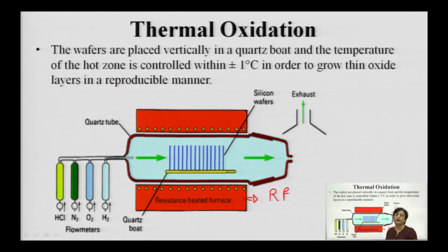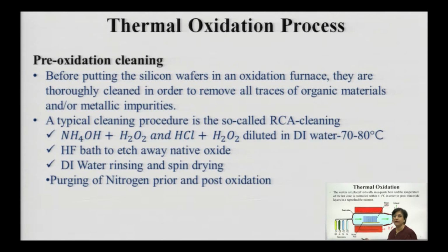to result in oxide growth, and for that very purpose you ensure that proper temperature is maintained. The wafers are maintained at a moderate temperature, so that the silicon wafers have exact deposition happening and there is no deposition onto the wall of the furnace. The entire chamber temperature is controlled within plus or minus 1 degree, and you will have thin oxide layer growth. Initially it is a linear rate, and it keeps on increasing linearly.